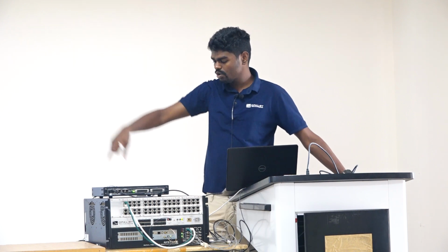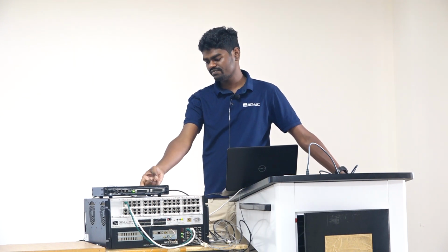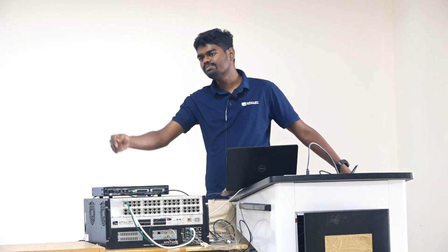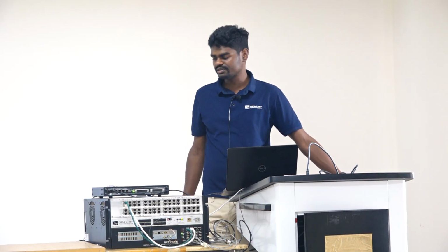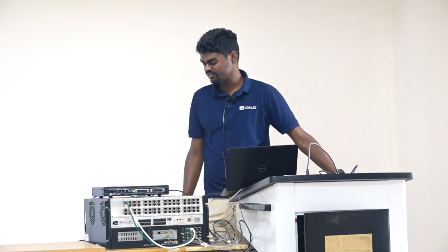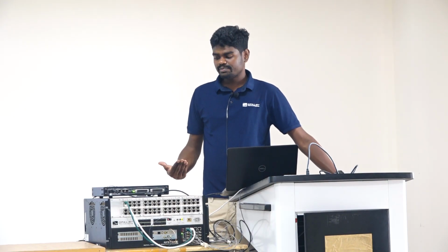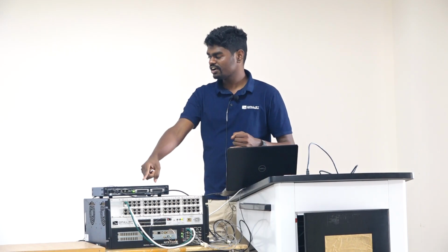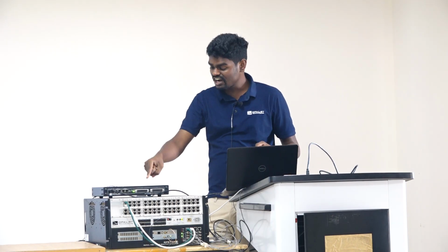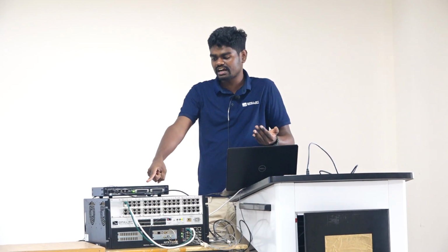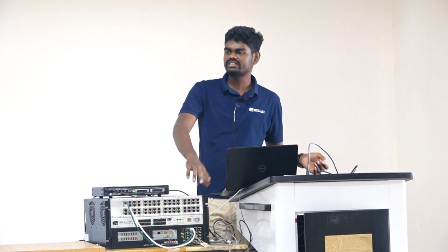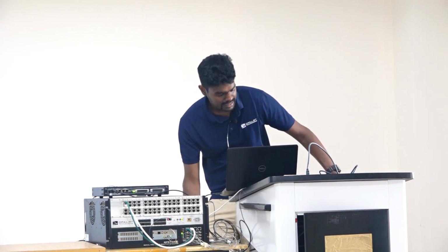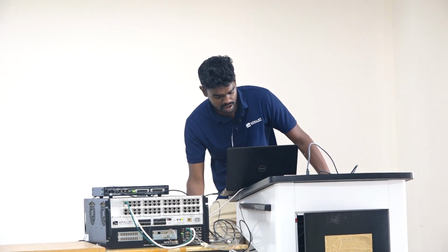Now this PWM will go to the digital output of the controller which you have physically here, and that will be physically routed to the digital input of your OPAL-RT 5700 simulator through the connection which we have here. So in hardware perspective, we have two connections: analog output from 5700 to the analog input of the controller, and digital output of the 8666 controller connected to the digital input of this 5700 simulator. So these two connections you have, and this is what the control model is all about.